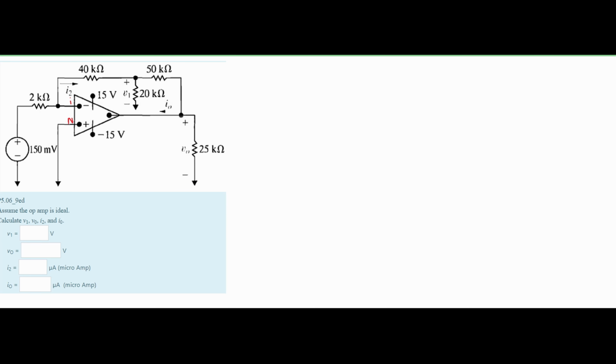When we look at this, the closest thing to our left side, because I like to look from left to right, is this I2 right here. So we can solve for that. This is going to be pretty easy because we have a voltage here and a resistance here. And we know by Ohm's law, voltage over resistance is current. And this current from this voltage and this resistor is only going to go to our I2 because no current ever enters our op amp. So no current's going to go through here.